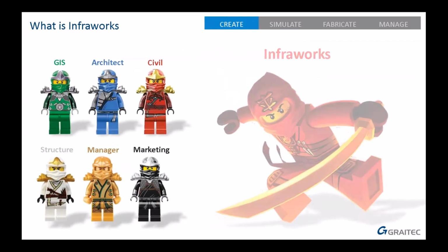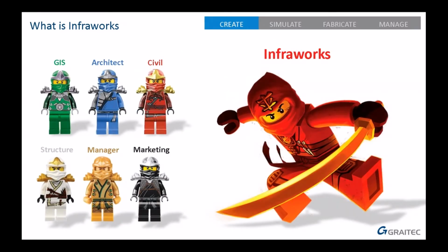Secondly, it's a collaboration tool. It's a place where you can bring together things like Revit files, AutoCAD files, SketchUp, it doesn't have to be Autodesk, Inventor, 3ds Max models. You can bring your GIS data in and do constraint checking like flood data or SSSI data, or are there any crested newts nearby, that sort of stuff. You can bring all these things in and it'll position them automatically if they're all georeferenced.